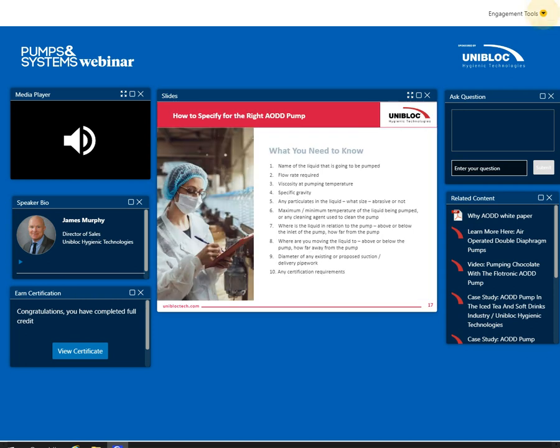All right, so let's get to the fun part. How do we specify the right pump for your application? So what do you need to know? So we've boiled it down to roughly 10 questions. The first being, what is the media that you're pumping? What's the liquid that we're pumping? What type of flow rate's required? What's the viscosity? Is it water? Is it 30,000 centipoise? Is it 200,000? So how viscous is it?